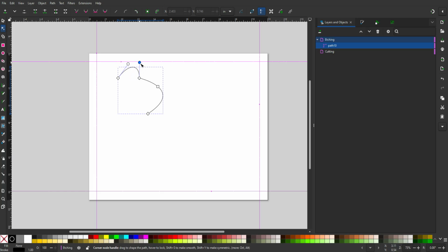And I think, can I make it straight in between? Break path, join segments, make node corner? Yeah, okay. So let's say I don't want this line in between them to be curvy though. I'm going to select this node and choose this make nodes corner. So that just gets rid of any curve. If I wanted to make selected nodes symmetric, let's see. You have to select all the ones you want to make symmetric. So let's do this.